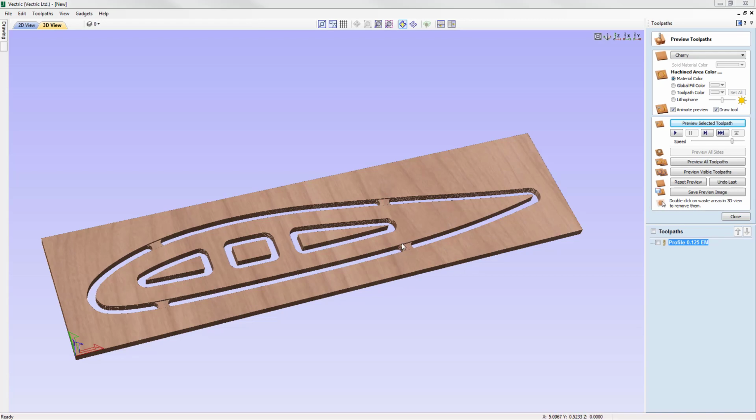we've added in there. However, there is one potential problem that I can see, and that is that we have loose waste material on the inside cutouts, which could rip away, ruining the inside cutout. It also has the potential to damage the tool itself, as the part is loose, so the vibrations of the machine could move that loose part into the tool, and it could also cause injury or damage if the loose part gets flung out by the tool. And so to avoid any of these problems, we could just look at adding tabs on the inside as well as what we already have on the outside.